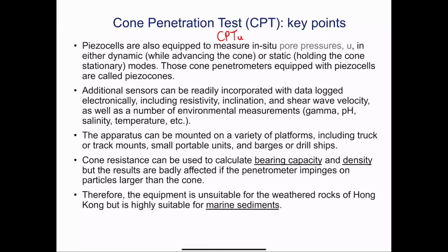Sometimes you can hold the CPT at a particular depth, and when you push it in, you'll generate excess pore pressures, right? You can hold it and see how long it takes to dissipate these pore pressures, right? Then you can estimate the permeability of the soil. You can even use it to get consolidation parameters. So think about how, if you do this in situ, it's quite useful. As I mentioned, it can be quite useful for environmental assessments.